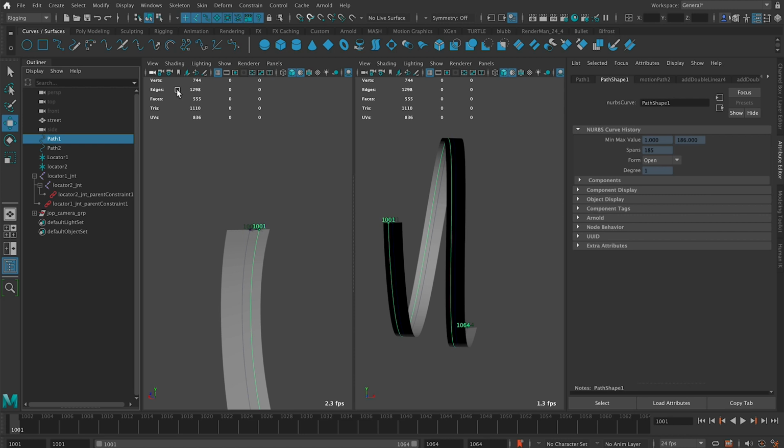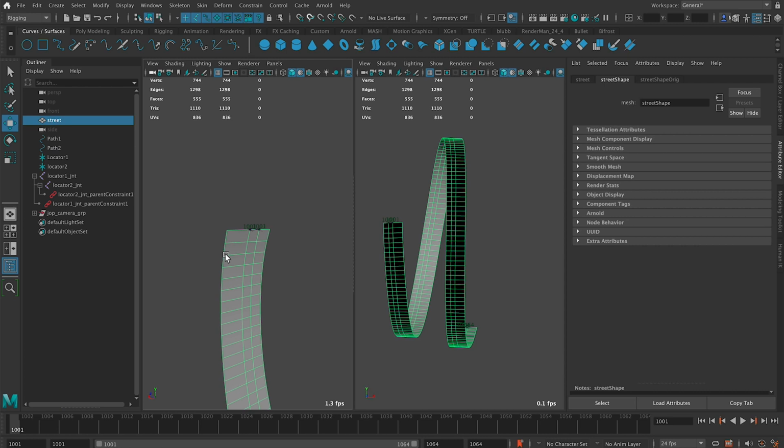What we're gonna do is use the surface of your street, which has a normal. Every polygon has a normal which is automatically calculated from its vertices. And we're gonna use that normal direction as the up direction of our object. That way it should be way more robust and there should be no flipping.